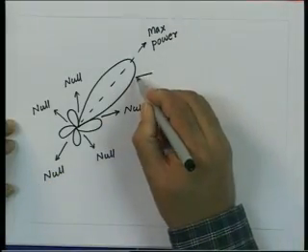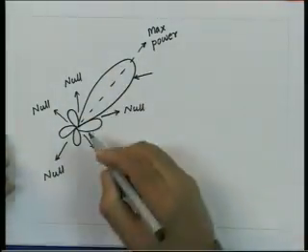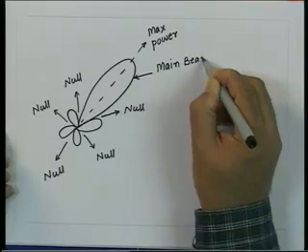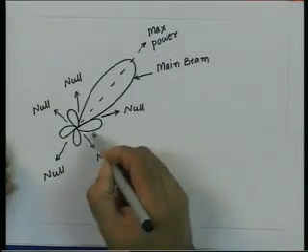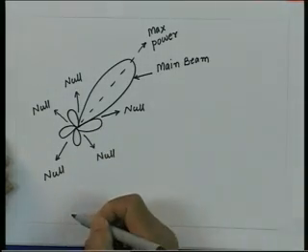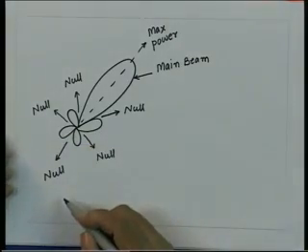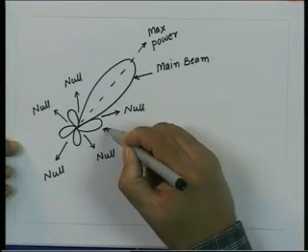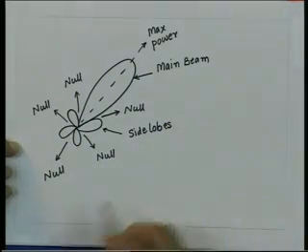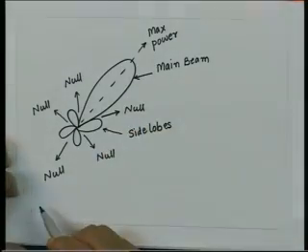So we call this lobe, or this angular region where the maximum power is going, the main beam of the antenna. And then all these minor lobes which you are seeing, the angular zones in which the power goes, again there is a local maximum, but this is much smaller compared to this. All these lobes are called the side lobes of the radiation pattern. So, in this case we have 1, 2, 3, 4 side lobes, and we have one direction of what is called the main beam.